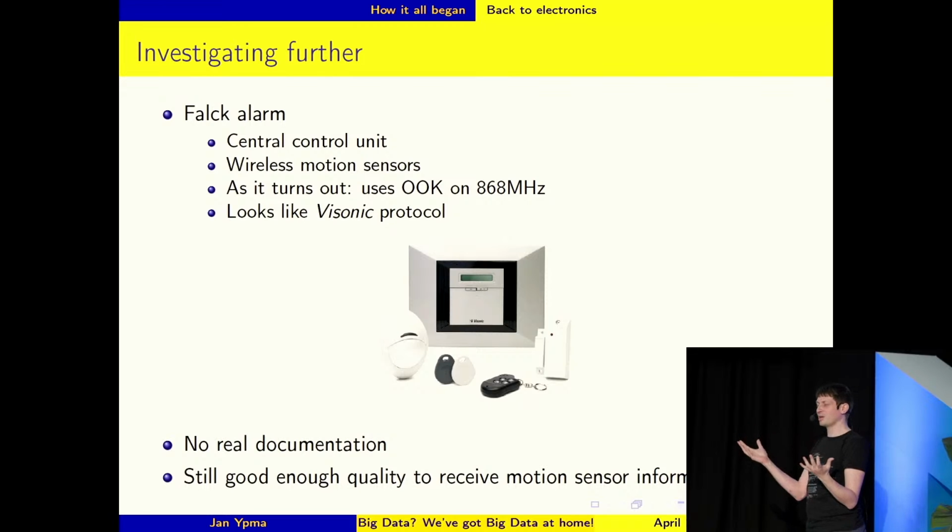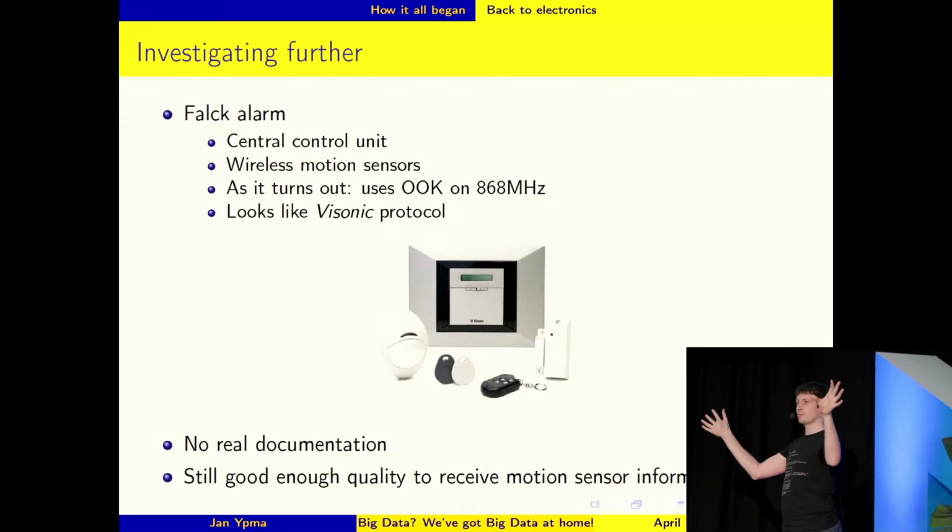That's how I realized, wait a minute, it's that motion sensor there that when I move, it sends out a radio signal and it's going to mess up my reception. Well, that's actually a good thing, because as it turns out, now we actually can use motion information, and we were working with the lights. So that's a fairly small step to say, okay, if I haven't seen any motion for whatever long period, then let's turn off the lights.